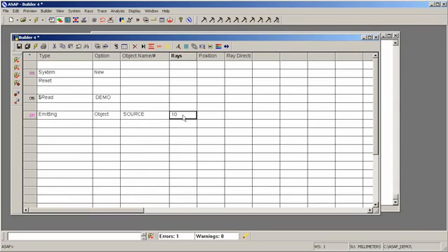The parameter on the right is the number of rays. I'm going to use the default here. Okay. Now, one thing we need to keep in mind is that ASAP is a surface modeler. Any surface has two sides. Okay. ASAP does not know beforehand which side is best for the user's application.